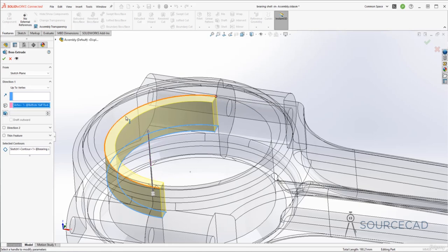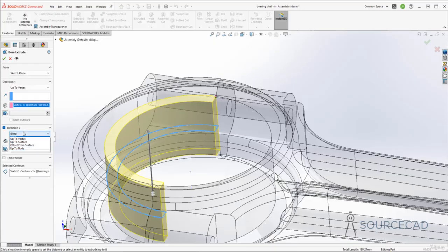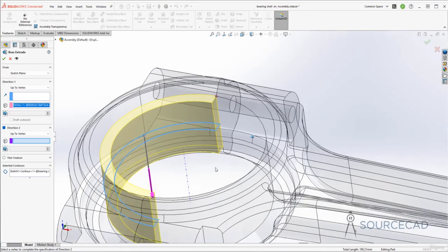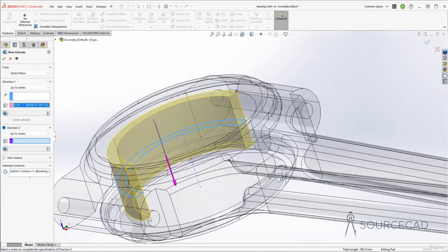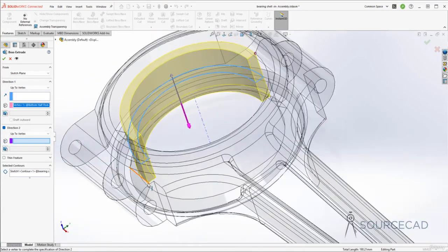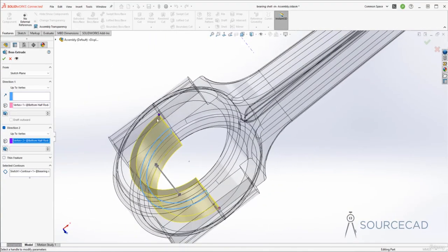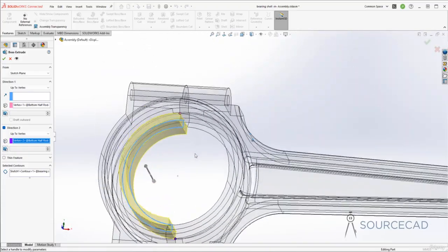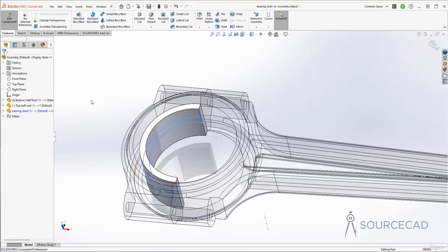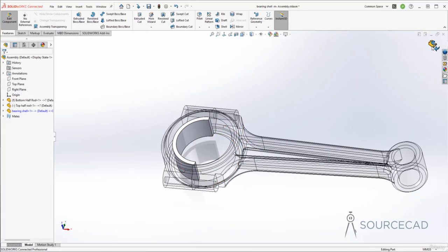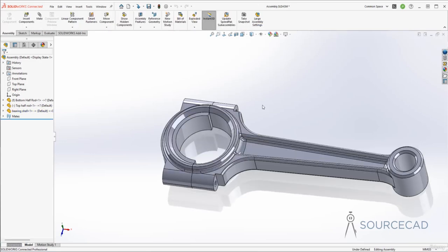And that's the height. We also want it to extrude in the second direction. So go to second direction. Here also select up to vertex and specify the second vertex. So in this case, the second vertex is right here. So we may need to just revolve it or just select the vertex from here. And it's right about here. So there it is. It is now selected. So we have selected vertices on both the sides and there it is. It's done. Click OK and we have it added. Now exit out of this part and we have this.